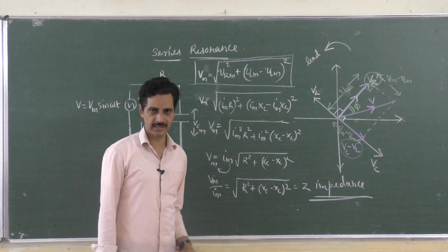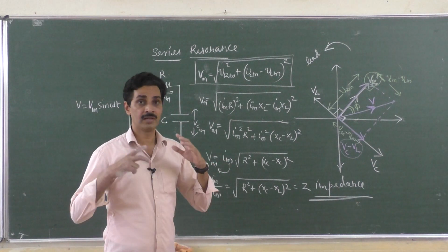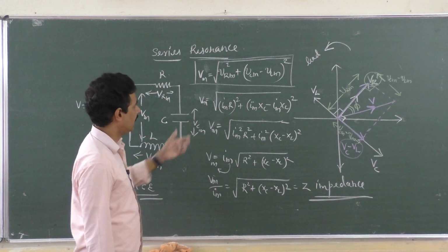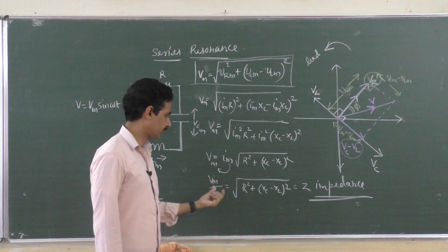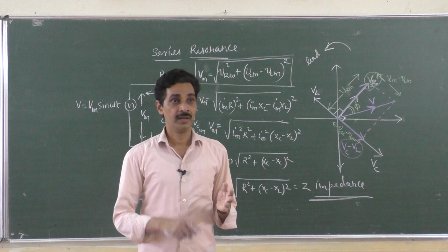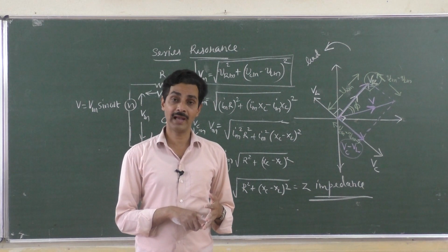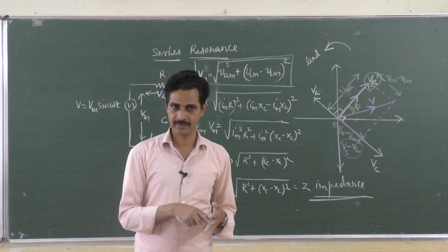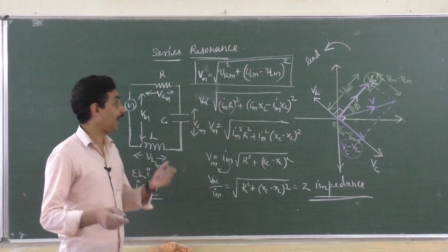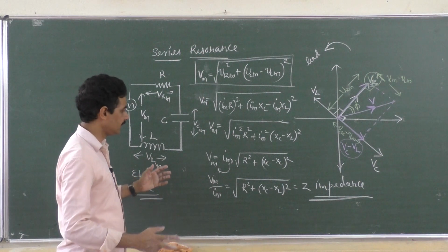First of all, find out the voltage. You may be asked to work out problems to find the total voltage across all the three components by giving individual voltages, and then you have to use this formula. You may be asked to find the total impedance of the circuit. We got resistance in ohms. Inductor and capacitor gave some resistance to the flow of alternating current, which we call reactance. But when we connected resistance, capacitor and inductor all together in series, we had resistance, reactance, reactance. Totally when you calculated it, it is impedance.